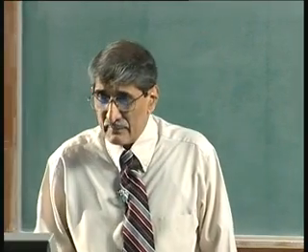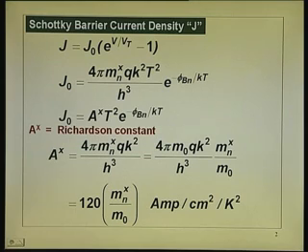What we have discussed here is that the current transport is through the transport of carriers over the barrier. All those electrons which have energy in excess of the barrier height will be able to give rise to current. Through that approach we said that J naught will be given by this expression, and the whole thing here can be put as a constant A star, because that depends on the material, since the effective mass comes in, and on the temperature. Temperature is absorbed here and A star includes the Mn star, and of course it depends upon phi b n.